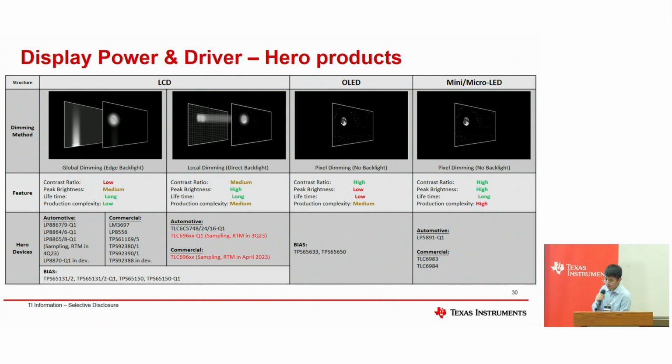The second one belonging to the liquid crystal is local dimming, also what we call the direct backlight. Different from spraying the light from the edge of the backlight modules, we have those backlight modules directly behind the pictures or the liquid crystal panels.